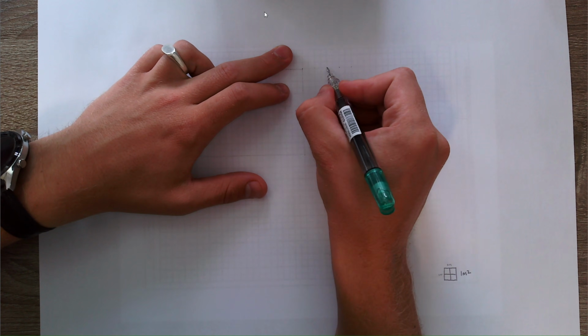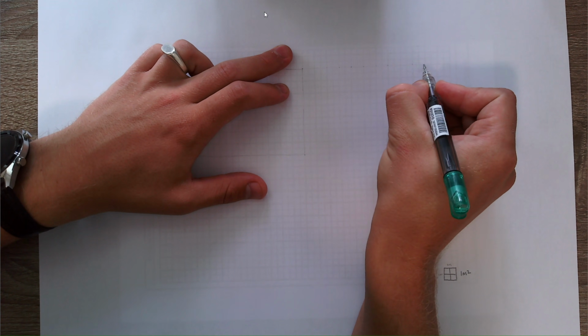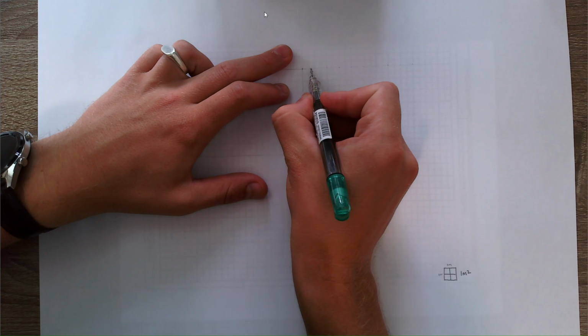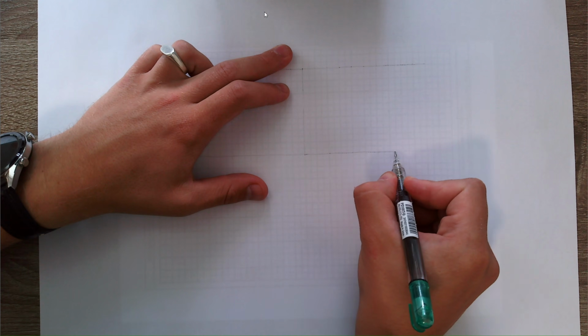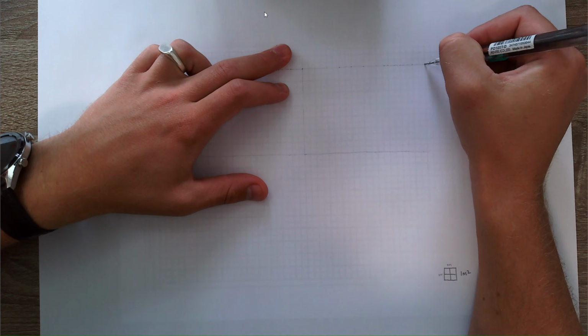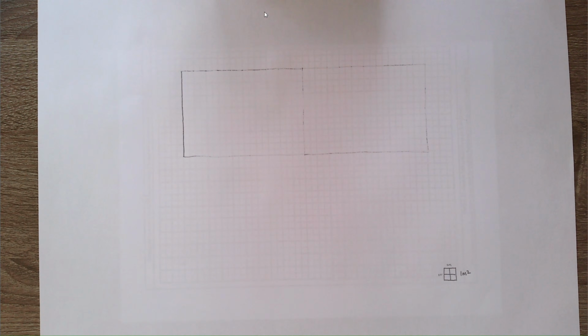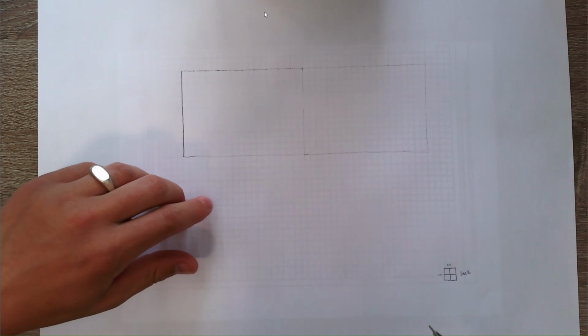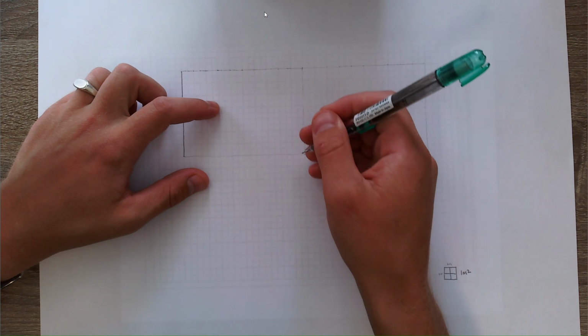So it's another 1, 2, 3, 4, 5, 6, 7, 8, 9, 10. I'm doing this light first because there's still a lot of information that you need to add, like doors and windows, but I just want to get the layout first. So that is how you're going to calculate the size of each room according to your area scale or proportional design. So we have a classroom 1, we have a classroom 2. Remember, you need to divide it with a room divider.